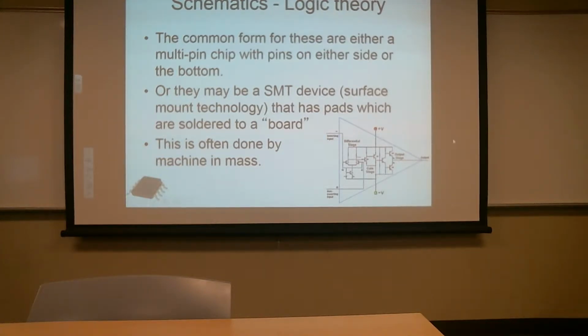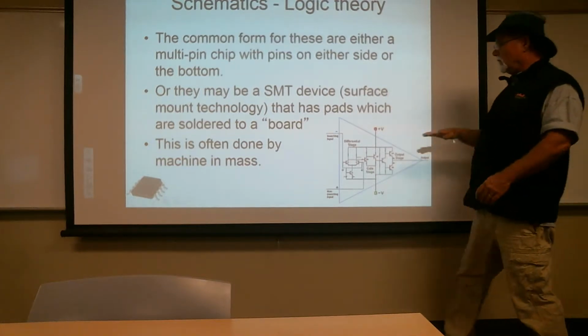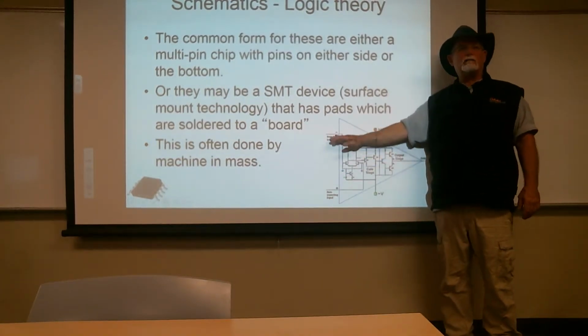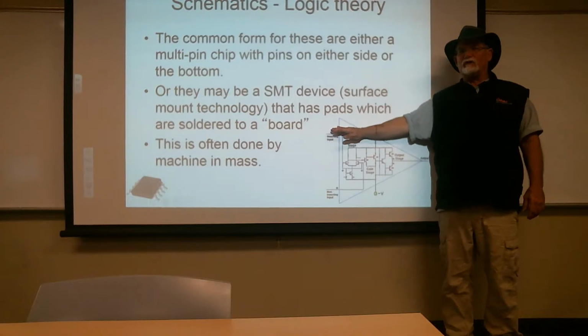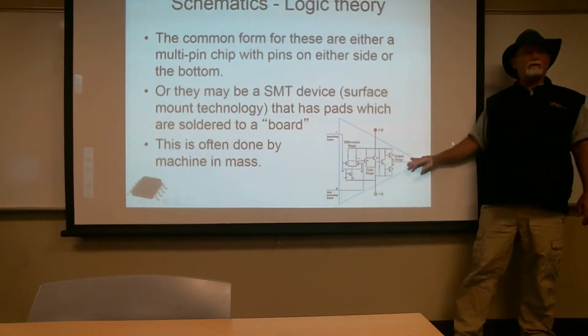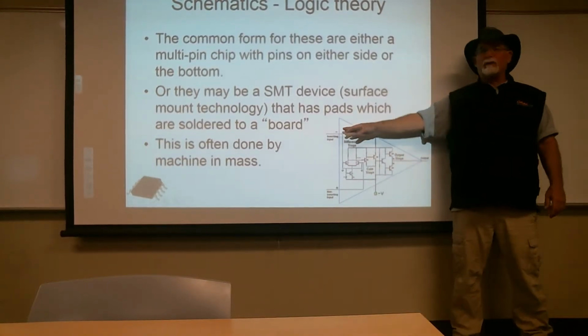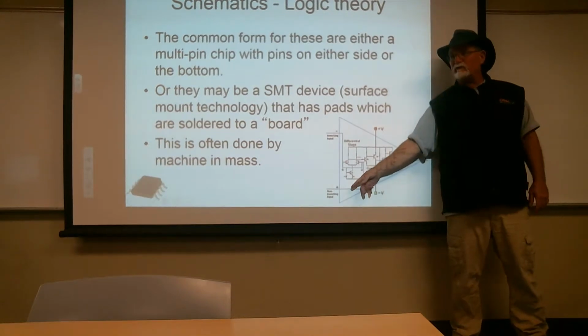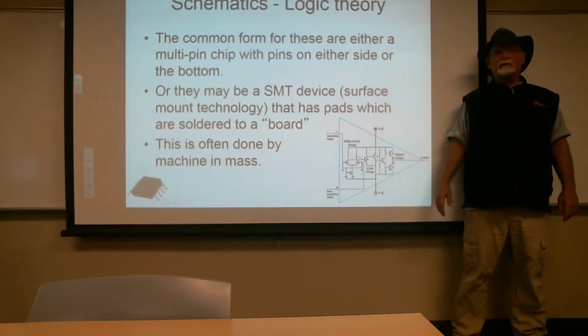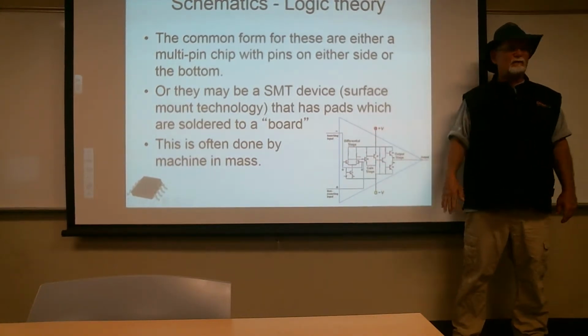On the other hand, if you use the non-inverting input to set a threshold, you can then use it to set the threshold voltage by which the inverting input makes its decision, the output makes its decision to flip based upon the input. So you can use this to set whatever that value is. You know, anything above 2 and anything below 2.